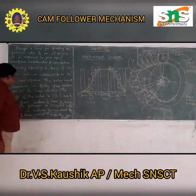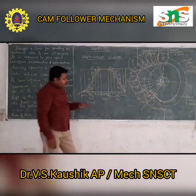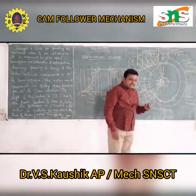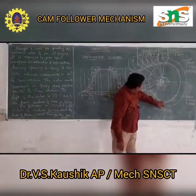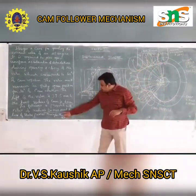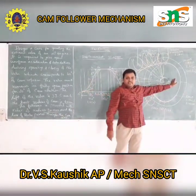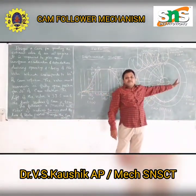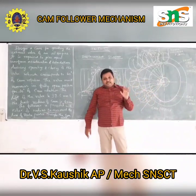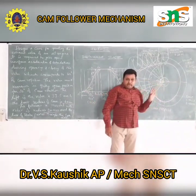And the line of stroke passes through the cam axis. The line of stroke passing through the cam axis means the follower remains as such. If the line of stroke is said to be 10 mm away from this or 20 mm away from this, that is offset. That is called the offset position. Okay, now we are clear.